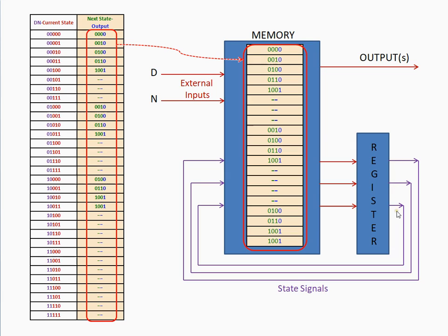So the three state signals will be the three outputs of this register, which is simply a register that latches on to the state and holds it steady until the next cycle, which will be represented by a clock pulse, which is not shown here, but a clock pulse should be produced to the register to register a new state whenever a new input happens to arrive.